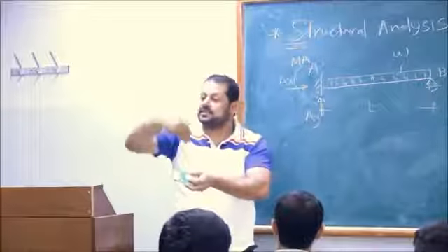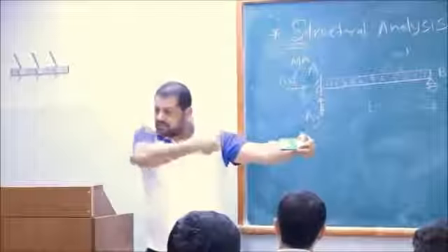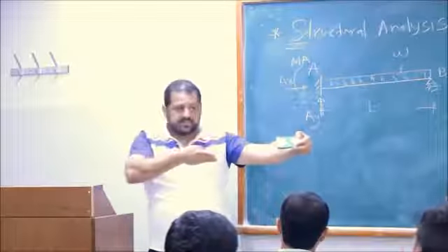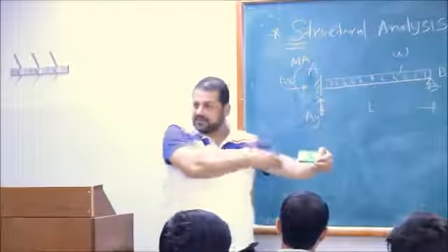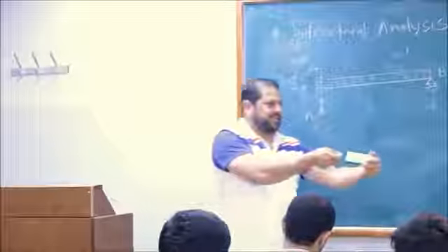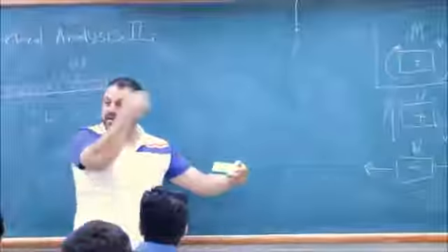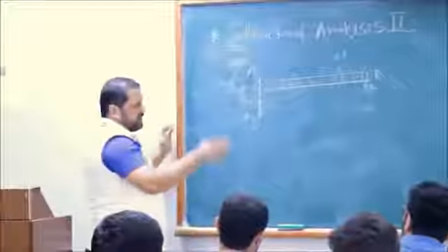That's the resistance to any force you have. When you apply tensile, what's resisting? You have tensile or compression. What's resisting? Cross section times E of the material. Cross section and E, not only the cross section. For example, if you have rubber or steel, it differs, even though it's the same cross section. So E and A. Anyway, I'm going to explain all of that.